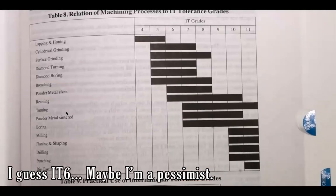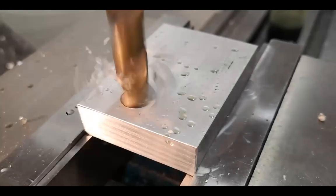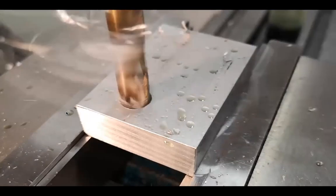Likewise, if you have to design something to fit inside a drilled hole, even if you don't have the tolerance for the hole in front of you, you can look up drilling and see that it has at best about IT10. So the whole basis for the fit is going to be around H10.